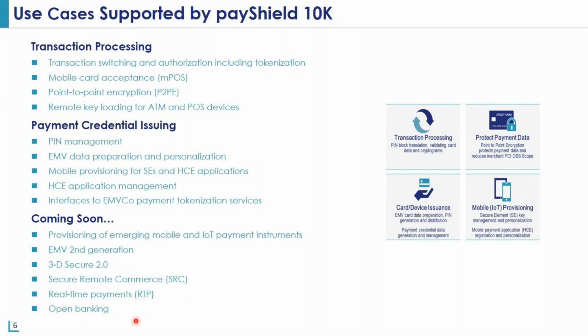And these are some features which will be supported in future. But let's say 3D Secure 2.2, I'm not sure whether the latest release, that is 1.6, has already supported some of these features. But please always have a practice that whenever you are installing a new firmware or a new software, you always check the CRN, customer release note. That customer release note will have information about what bugs are fixed in this particular release, what features are added, and what features are removed. So the customer release note is a must-read document.